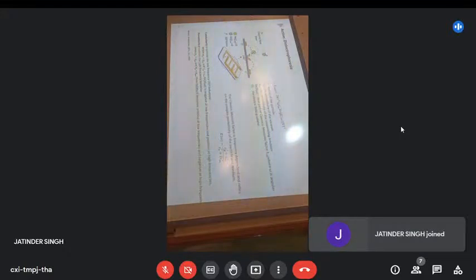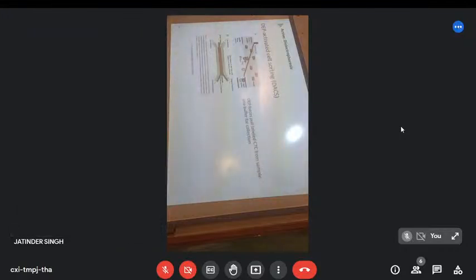So the permittivity controls the high frequency behavior, the conductivity of the media is the low frequency behavior. So depending if we've got positive dielectrophoresis, when we want to go with particles want to concentrate close to the high density, other particles will want to preferentially go to the lower density fields. So we get different particles go to different places, which is always good because that means that allows us to sort things. So here we've got a dielectrophoresis system where we want to sort out some particles from others.